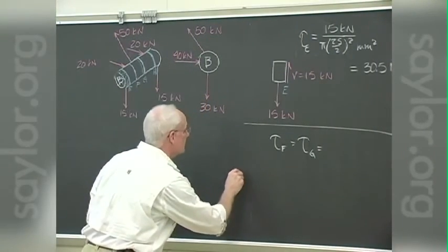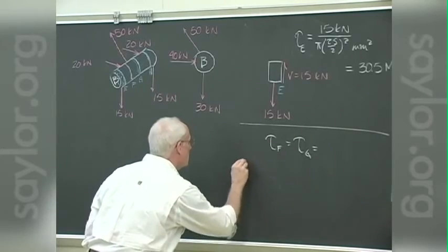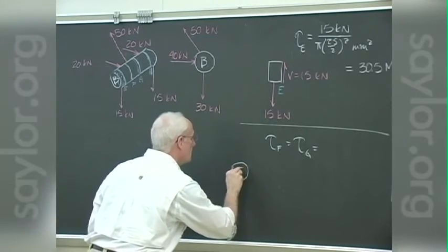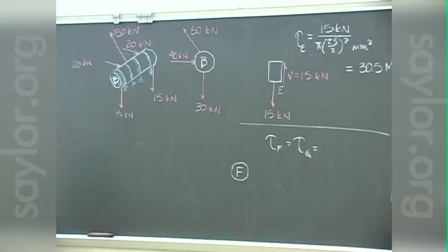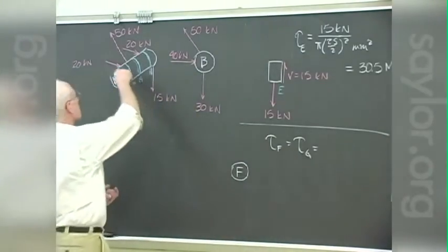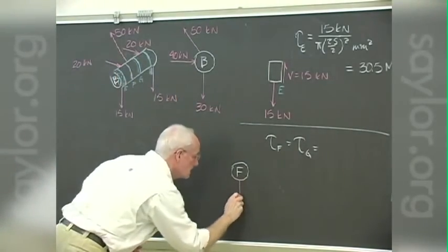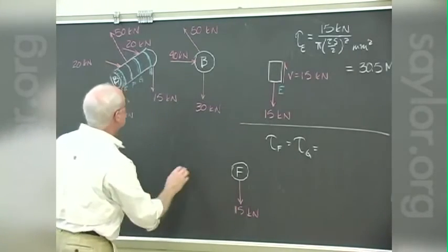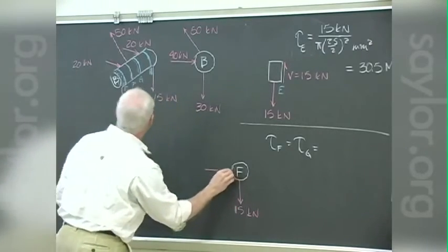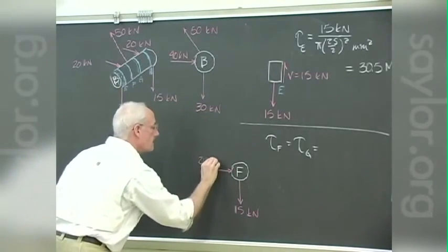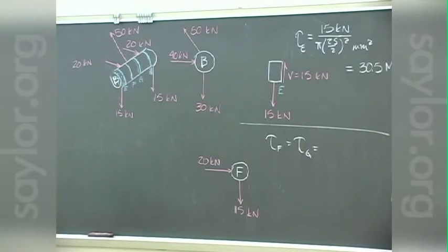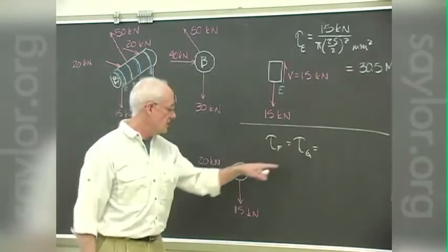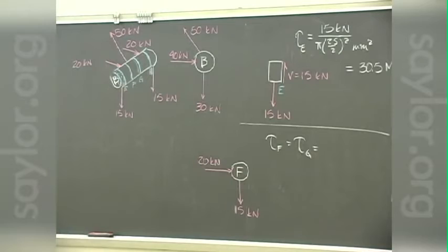Let's see, this one's probably easier to look at on end, because it's got the two loads like that. It's only half of the loads from the members because there's two sides maintaining this. Both F and G are resisting this, so we only put half of the loads there.